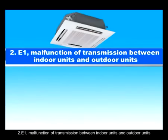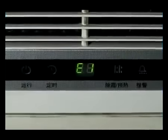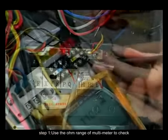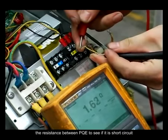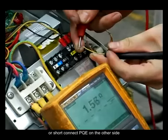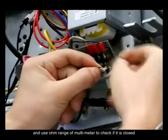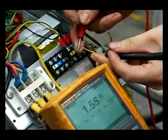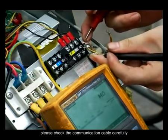2. E1, malfunction of transmission between indoor units and outdoor units. Repair instructions when E1 appears. Step 1. Use the OHM range of multimeter to check the resistance between PQE to see if it is short circuit, or short connect PQE on the other side, and use OHM range of multimeter to check if it is closed, to confirm if the communication cable is broken or not. If short circuit or open circuit happened, please check the communication cable carefully.